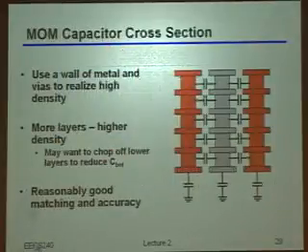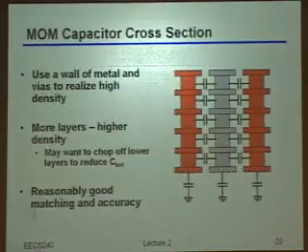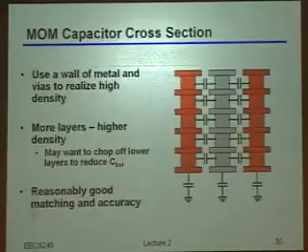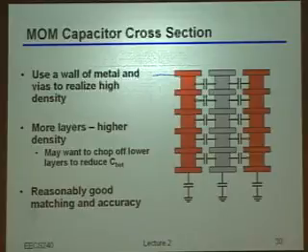I don't have an exact picture of that, but this picture that I'm drawing here may help to answer that question. If we take this same structure and slice it right along here and turn it on its side, so we look at the side view of the whole wafer, it would typically look something like this. So you have a metal line, a via, a metal line, a via, and so on and so forth. And that's how you build up this full vertical structure. Now, in the instance you were talking about, rather than, for example, this top piece looking like that, it would have to look, for example, like this.